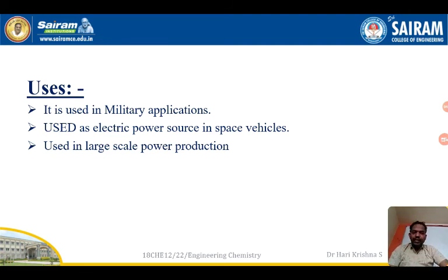What are the limitations? As discussed earlier, the methanol and oxygen are stored separately in cylinders, and care should be taken that the methanol pressure is monitored. If pressure is not monitored, the cylinders may explode. Therefore you are supposed to monitor the pressure. While allowing the alcohol to enter the fuel cell, the pressure should also be monitored. If pressure is not monitored, even the fuel cell may explode. Therefore monitoring the pressure becomes a very important task.